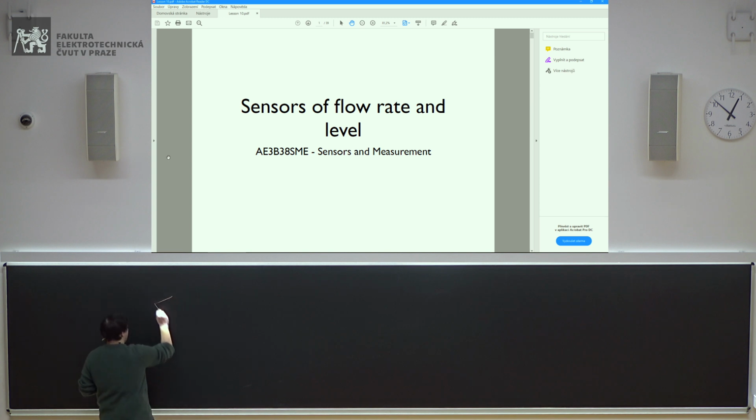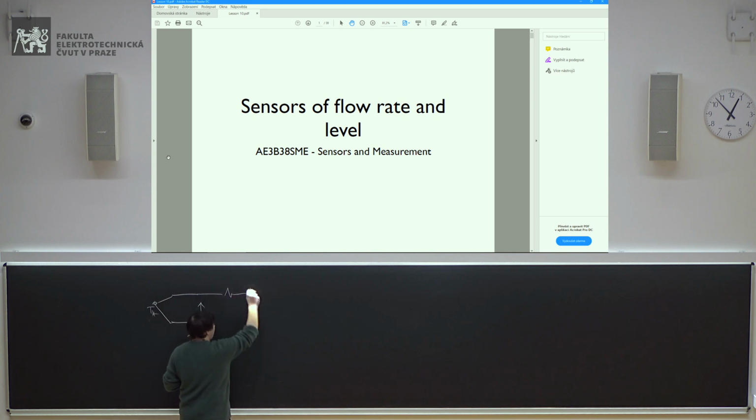I was amplifying the voltage of a thermocouple. So I had my thermocouple here. As you know, well, you still don't know because it will be the topic of the next lecture next week, but I've already explained in the virtual laboratory that you have an output voltage which is proportional to the difference of the temperature between the hot and the cold end, and I amplified this voltage using an inverting amplifier, which is something that we have studied multiple times now, okay? Let's say that we want to amplify it 100 times.